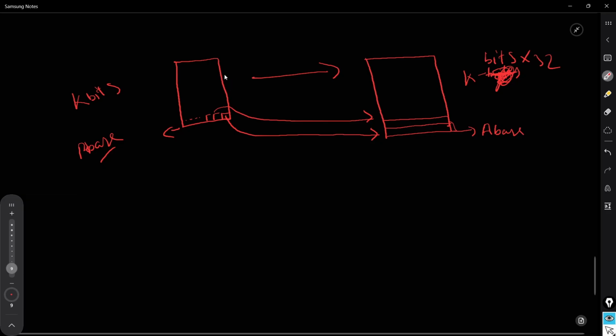Now say you need to write to a specific bit in the peripheral region. This is that specific bit. So obviously you will have some offset. This value is the offset in bytes. I will write it as the byte offset, and you will have some offset in bits. Say you wanna write to the second bit, so this is the bit offset.